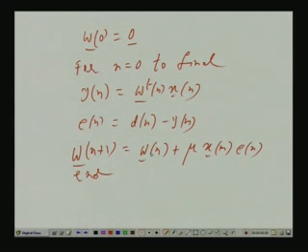You see, the moment we replace I by n and use some real time estimates for the R matrix and P vector, everything is data dependent. Okay. There is no E operator here, there is a direct data vector x n multiplied by W transpose giving y n, then E n, and x n vector is used along with E n to update the weight for the next index, so on and so forth. This is an adaptive algorithm. So we do not need any longer any information about R and P.